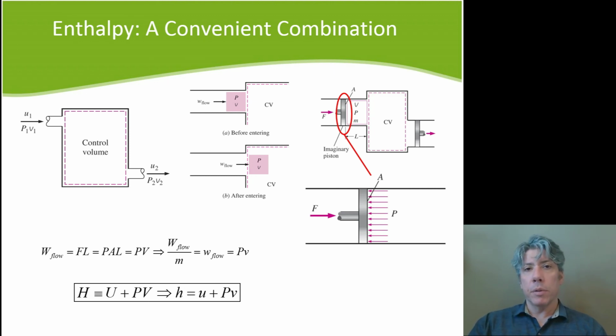All air-powered tools are really thermal energy type machines. They use thermal energy to do their work. Now, typically we'll let it flow, and we extract a lot of flow energy from it. But the point is that flow energy and thermal energy appear together when a fluid is flowing. When a fluid is stagnant, you should not think of the energy in that tank as being PV energy, pressure times volume energy. That is a big mistake. And I've seen engineers that have practiced for years make this mistake, but that's not what it is.